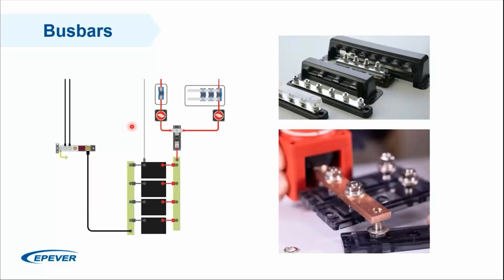If using a busbar, its thickness should be calculated as well. It's like a cable and should tolerate the current capacity that you need in your system. To calculate busbar thickness, simply use the recommended cable surface area and apply that to the busbar cross-section area. So you have a width, a height, and a length.